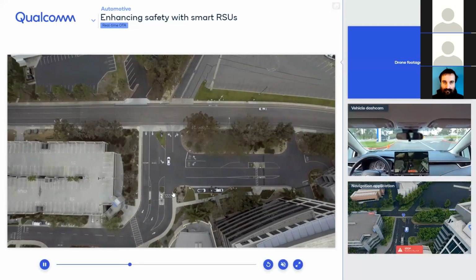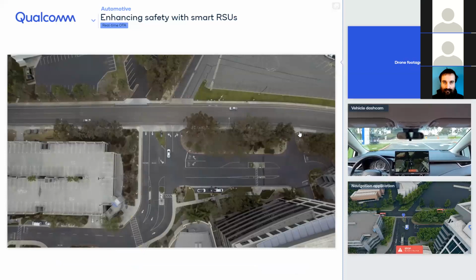So it can detect these two approaching. Now this car is approaching very closely to the T intersection. Then it can become dangerous to this vehicle, which is also approaching the intersection, and the vision is blocked between these two, right? So they cannot see each other. Because of this, the RSU starts flagging these two approaching vehicles as dangerous, and then issues a stop warning to the ego vehicle.